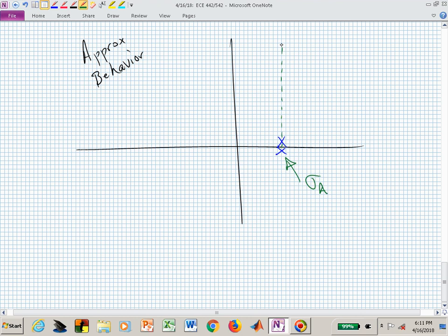Well, now if I have two poles on top of each other, I know that they're just going to go zipping apart as I get K bigger and bigger. And these dashed lines would then be my asymptotes for the approximate behavior of that three-pole, one-zero pattern far, far away. Now, how do I know that that's true? If I put a point there, and it belongs to the root locus, what do I know has to be true about that point, that red dot?